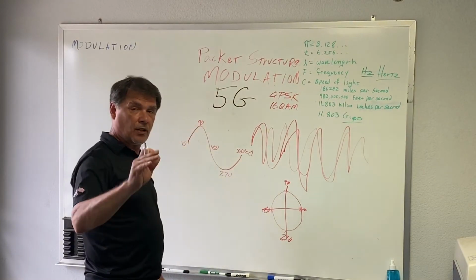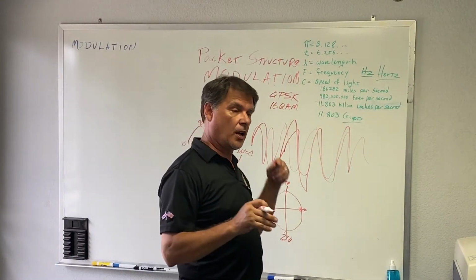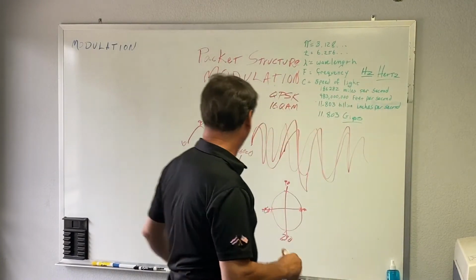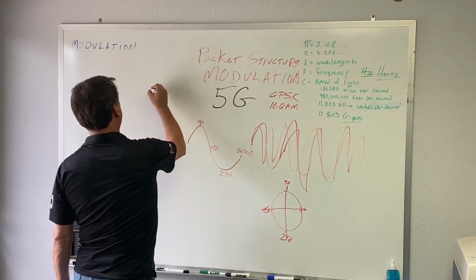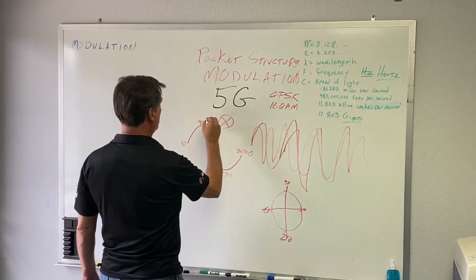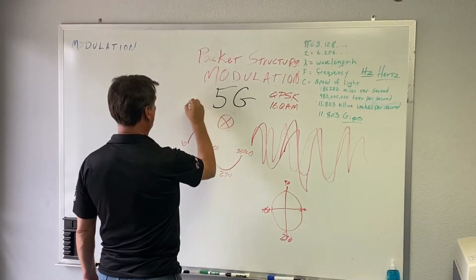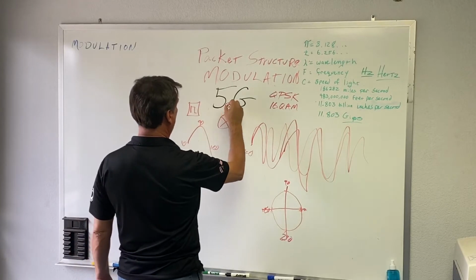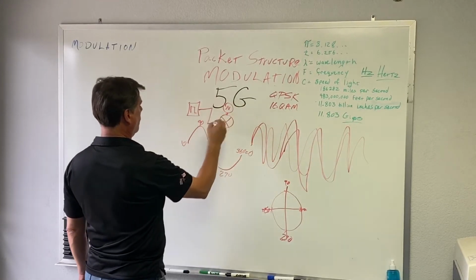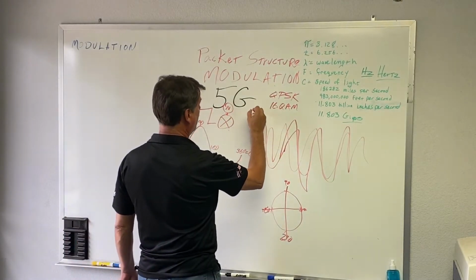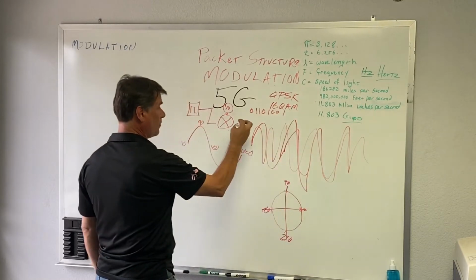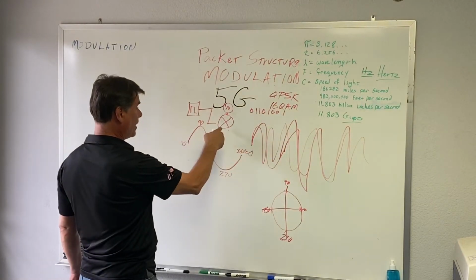Now we're going to modulate this thing. And what we're going to do is we're going to just take one stream of data and we're going to tell it to flip the phase 180 degrees. So when we put that digital 1 in there, right here will do. We've got a digital square wave generator, and we've got our oscillating source. We'll look at a timeline of 0, 1, 1, 0, 1, 0, 0, 1. So this is the data bits that are going to be coming into here.